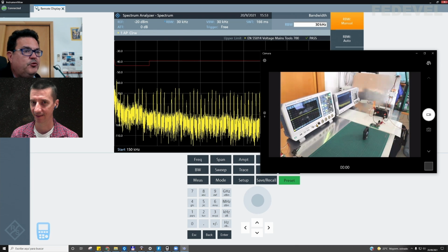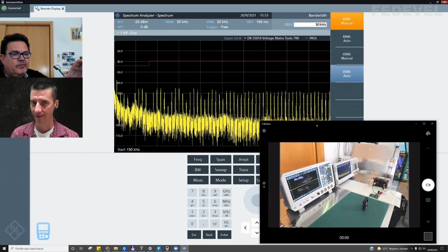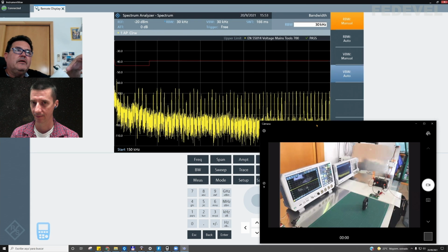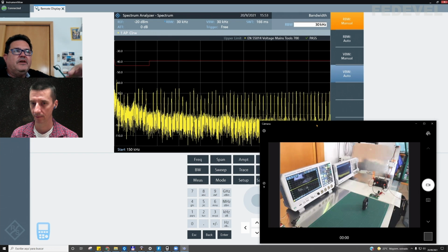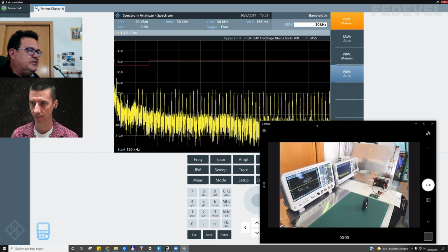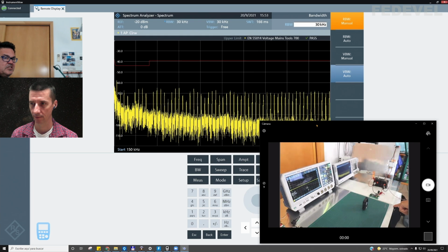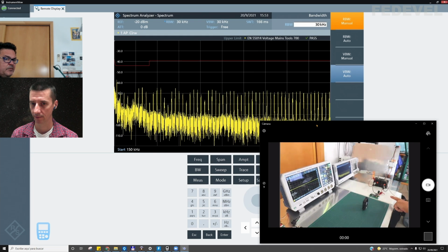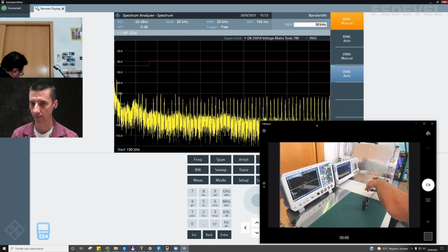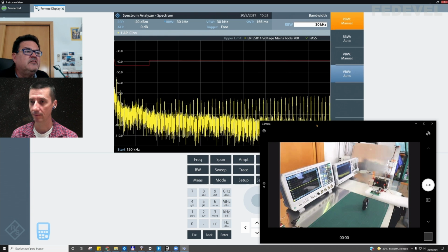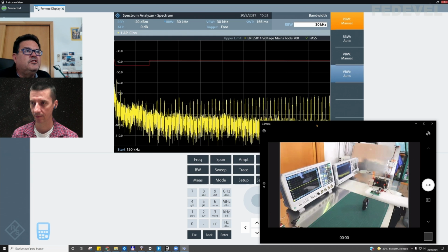This is very important. If you touch the device, you are working like a part of the circuit for the common mode, so you can affect measurements. But let me repeat the test without touching. So this is the situation when the device is very close to the metal plate. This is the situation with the distance, and I remove my hand. And you can see the difference, no?